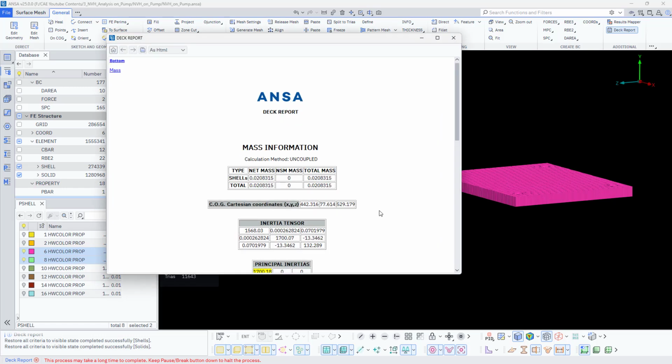Here, if I see it, it's approximately 20 kg. 20 kg is too much, right? If you could save at least 10 kg for automotive components, even saving 1 kg is more than sufficient for the whole model. So per motor assembly, if I could save 10 kg, it is fabulous, right? Now at 20 mm thickness it is 20 kg. If I consider 30 mm thickness, then it is approximately 30 kg.